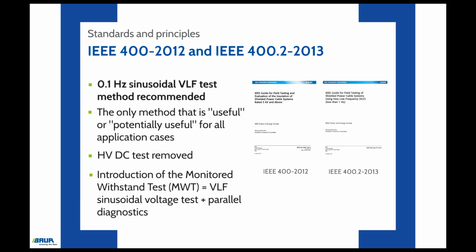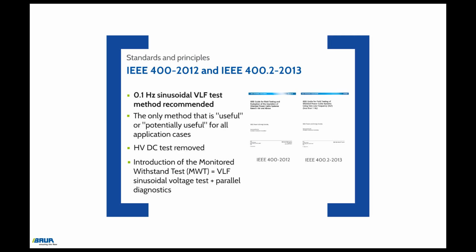Following the introduction of IEEE 400.2/2013, the tan delta monitored withstand test was introduced onto the market. This means the performance of the VLF sinusoidal voltage test with simultaneous diagnostic measurement.